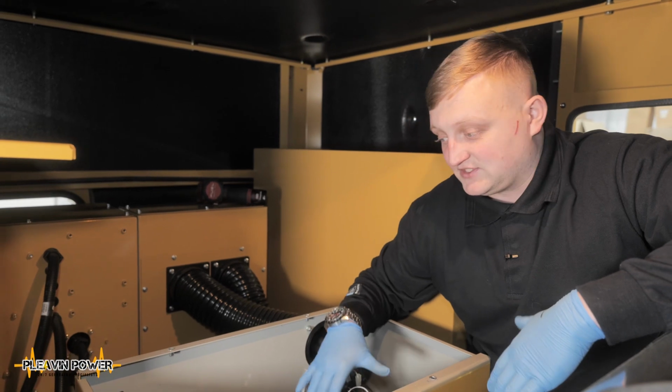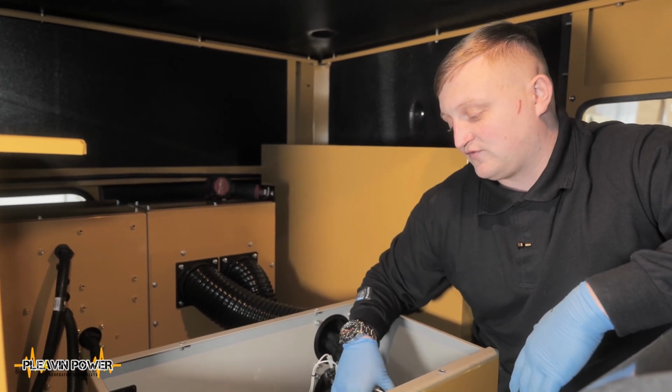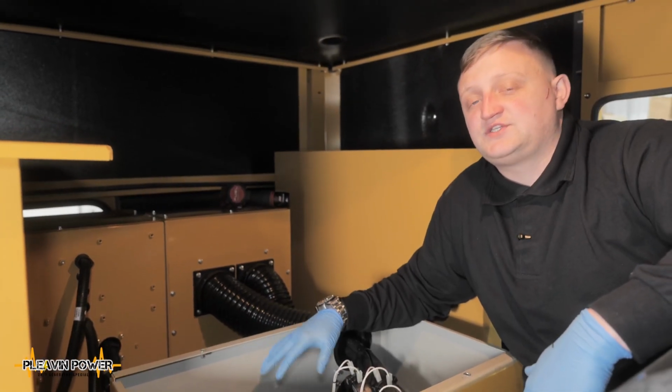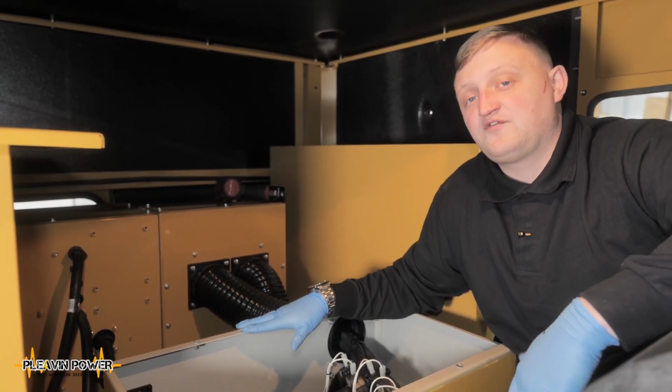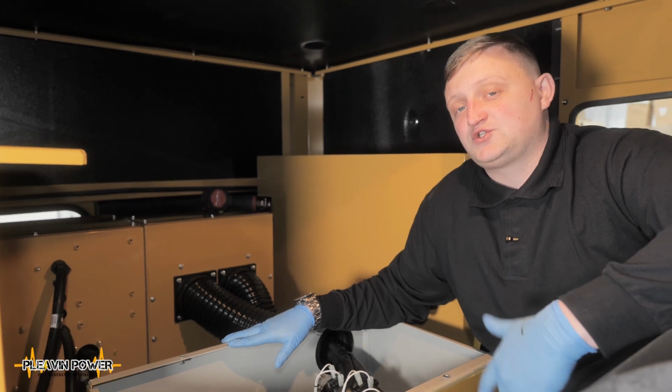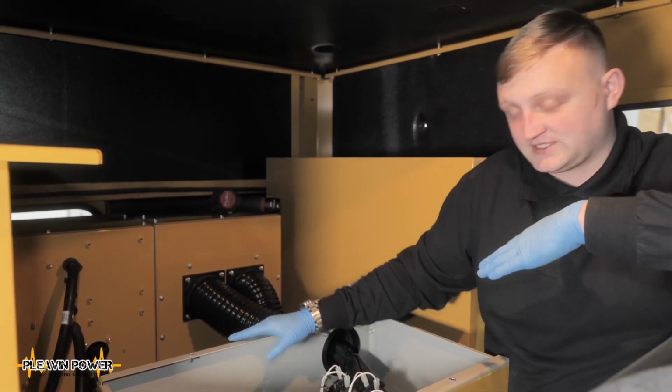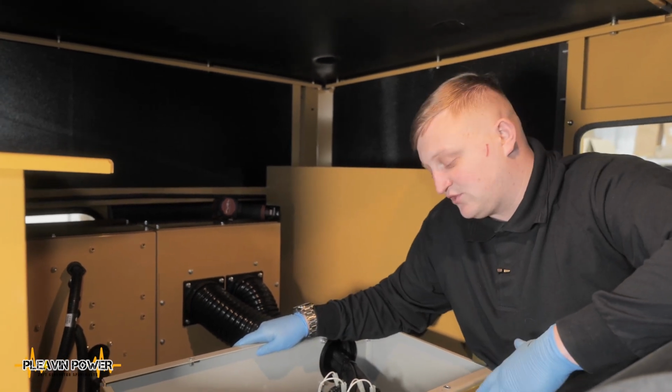Alternator maintenance is very important to ensure that the plant doesn't suffer any failures as a result of maintenance that hasn't been carried out. There are 3 things you need to check before you enter this cabinet itself. You need to be electrically competent, you need to ensure the engine can't start, and you need to have a piece of equipment to prove dead within the alternator terminal box itself. Then you need to move on to your maintenance tasks.